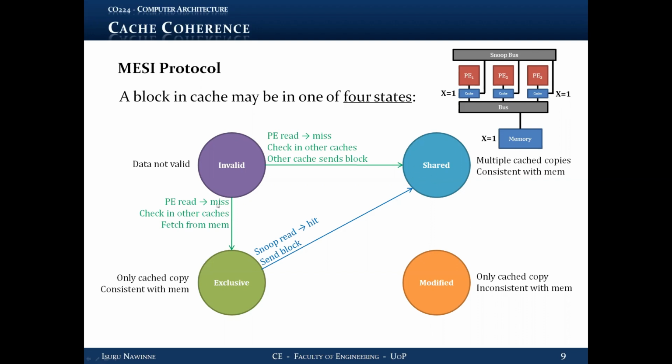So note the difference of what happened with cache 1's controller in the previous memory access. No other cache controller responded positive. We had to go and fetch from the memory. So the block was marked from invalid to exclusive. For the second access here, cache 3, the block transitioned from invalid to shared because another cache controller supplied the data, right? Okay, so that is the second access.